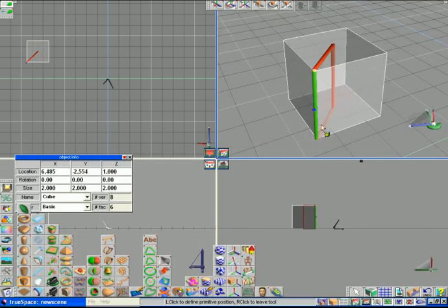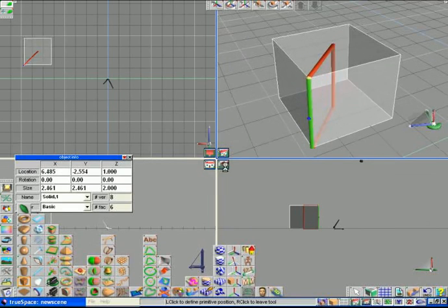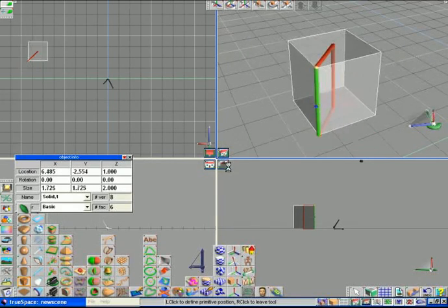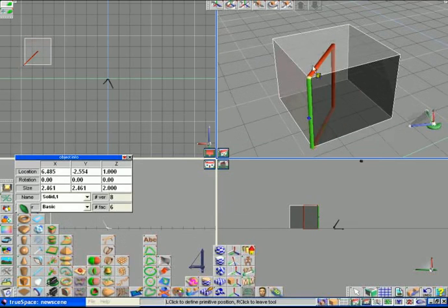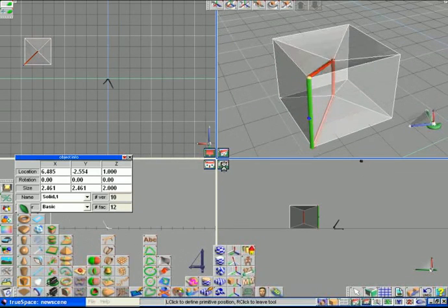This ring here is called the magic ring. Within TrueSpace you can use this ring to define specifically how this cube will look. Using the mouse you can highlight this ring and make different kinds of changes. For instance, if you click with your left mouse button, hold and drag, you'll notice that I'm sizing the cube if I click on the top portion of this red ring. If I click and hold on this vertical portion, I'm actually increasing or decreasing the top faces here.